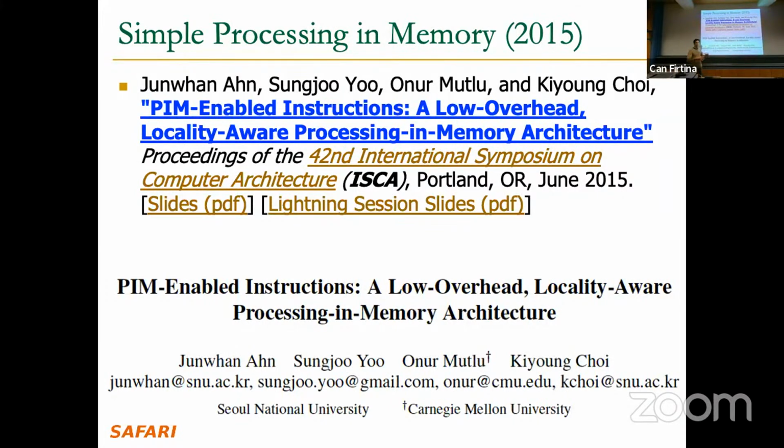Here, instead of creating a coarse-grained accelerator that is very good at something like graph processing, this idea is simpler: let's detect a few instructions, maybe an atomic addition, maybe a hash table query, relatively simple operations, or a distance calculation, something like that. And let's create a small specialized unit for this operation inside the memory, right?